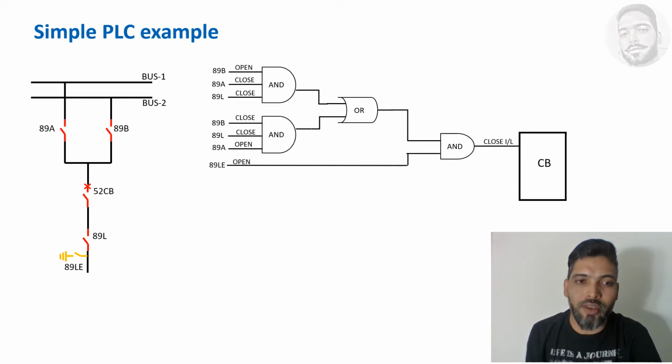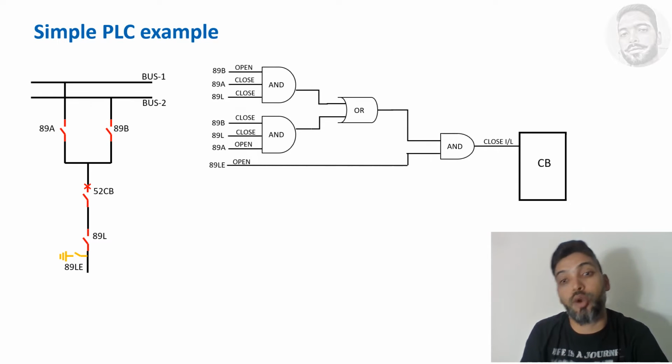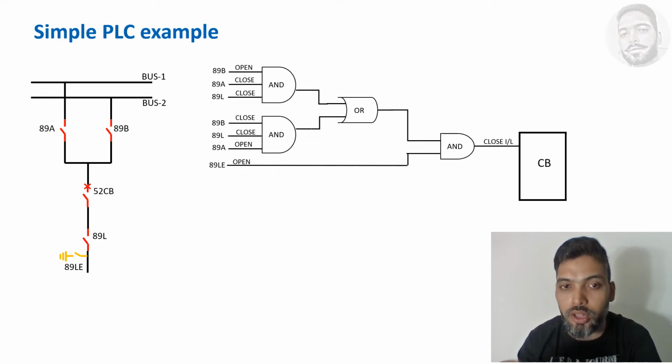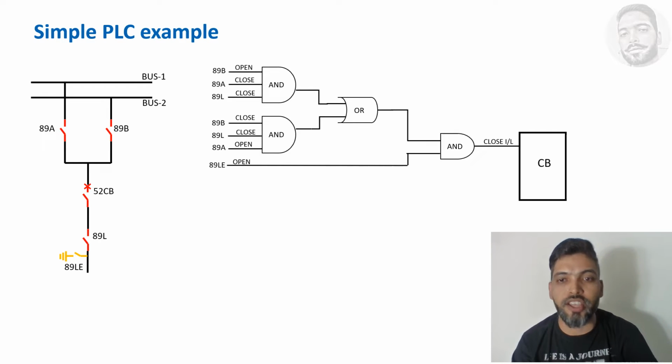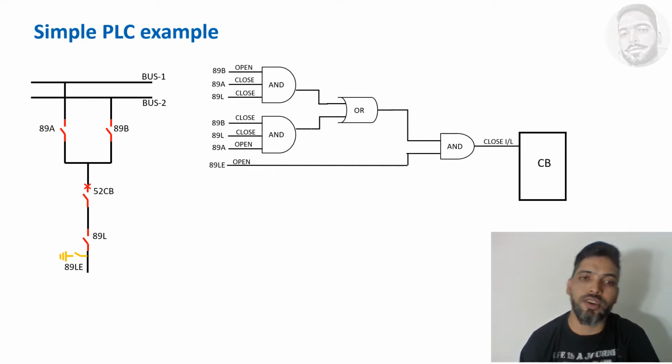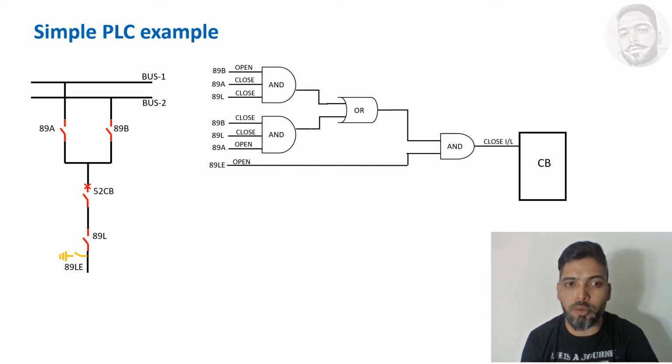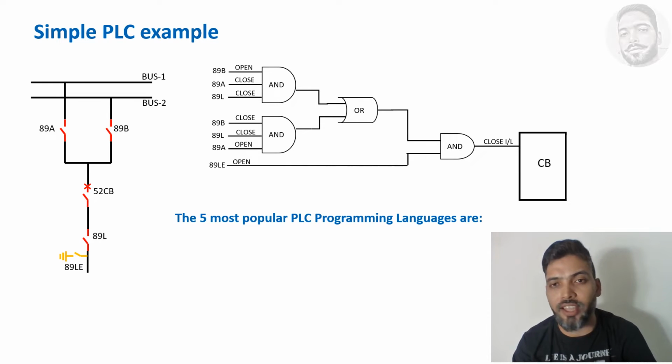For opening a breaker, we need not check anything, but for closing a breaker, you have to check everything, all these things. Then only you can close. Otherwise, it will be an accident. So all these things should be there. Generally, this type of scheme you will find in a numerical relay also, but I've taken this one as an example.